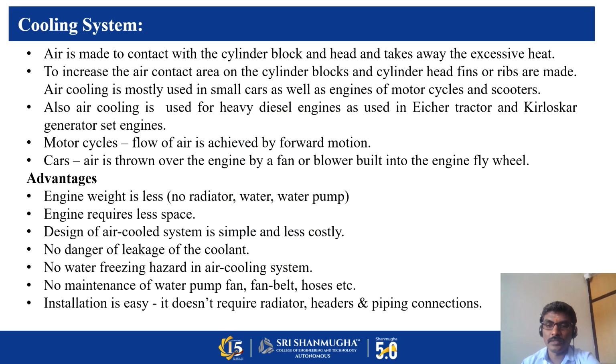Then cooling system. Air is made to contact with the cylinder block. So normally the cooling system is classified into two types, air cooling system and water cooling system. So air is made to contact with the cylinder block and head and take away the excessive heat. So normally in two-wheelers during the time of running, it has fins over the surface of the cylinder. To increase air contact area on the cylinder block and the cylinder head, fins and ribs are made.